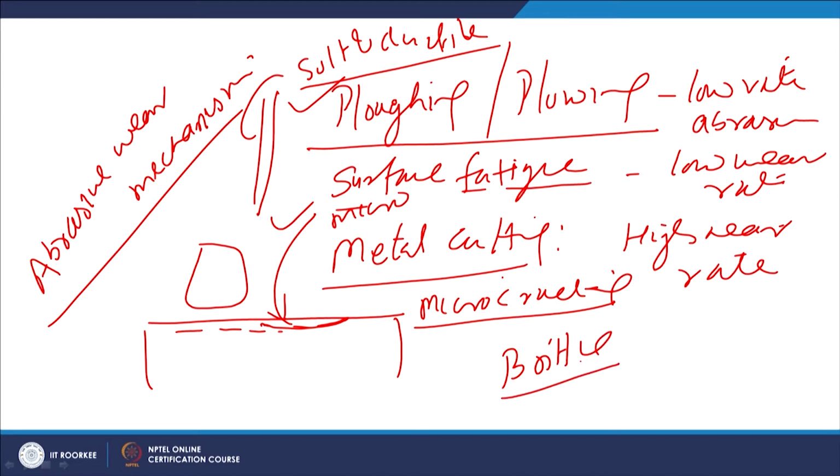However, under actual abrasive wear conditions, there will always be a combination of ploughing, metal cutting and micro cracking, as per the kind of material being considered. So, in which way can we express and schematically understand these wear mechanisms? For that we need to see certain diagrams.